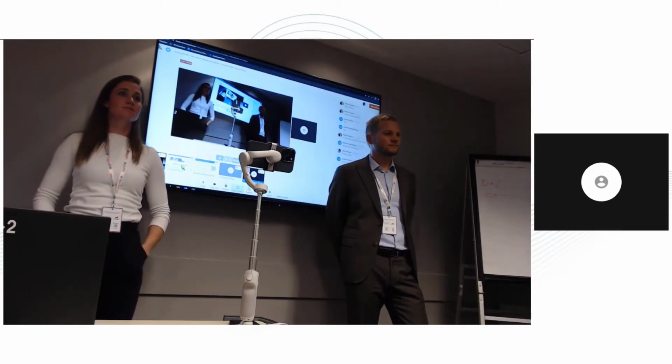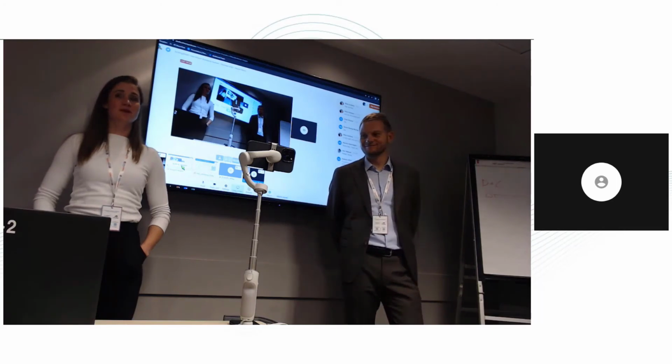Well, it is common to have to deal with 2D information, but you always have a choice to translate it into 3D, or to just use the 2D information. In this situation, we thought, okay, this is a very specific thing. We agreed with the client that we load it into Navisworks, we look from above, and if we see an interface with, I don't know, some staircase going up, it's always a clash. So it's kind of a manual check. But still, for the clash detection, you use Solibri. Yes, for the rest. Thank you.